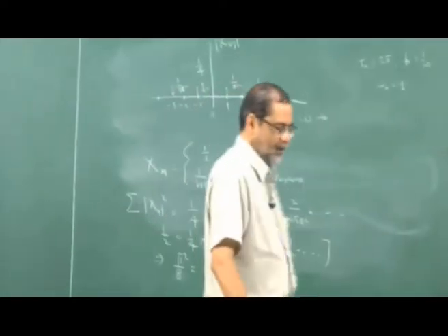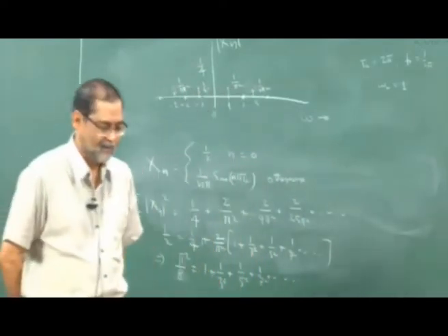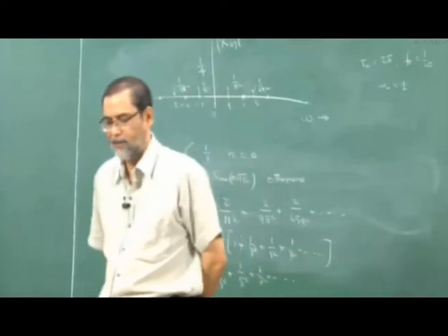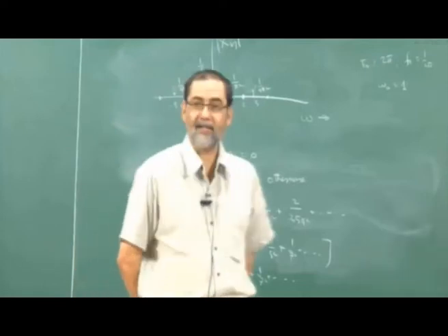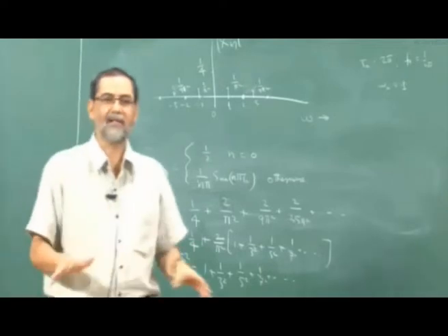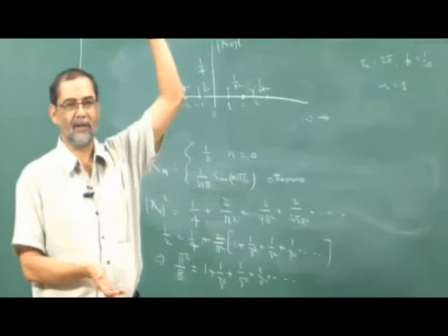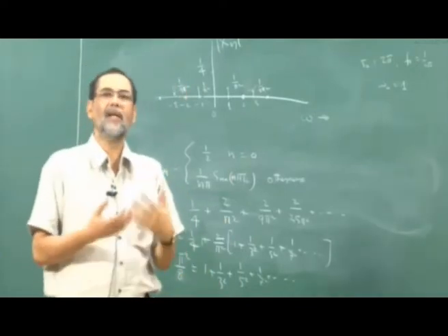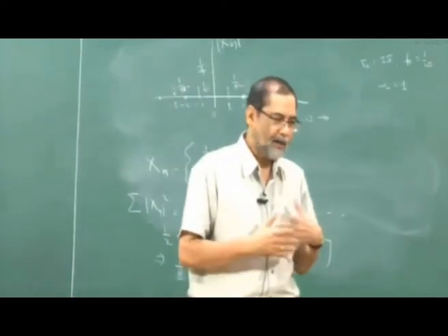Okay, so the question is, can you give a simple example, right? I cannot give a simple example, right? The reason is, the signals we study, the signals we are interested in, the signals we see in nature, they are all normal signals, do not exhibit abnormal properties, meaning they do not go to infinity, right? They do not have an infinite number of discontinuities, meaning they do not have an infinite number of maxima and minima within a period, okay. So I cannot give an example.